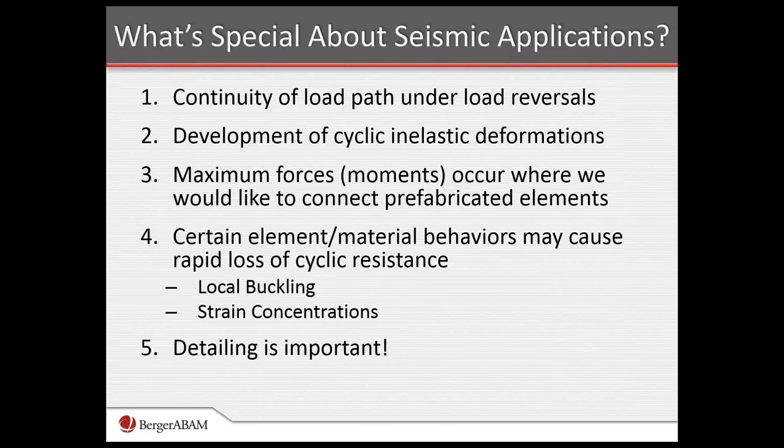We also, for higher seismic locations, are going to need to develop cyclic inelastic deformations, and the maximum forces, or in this case likely the moments, the way we think of this, would potentially occur where we'd like to connect prefabricated elements. We'd like to transport these elements as single linear elements, and therefore the connection location is often the same point where the maximum moments occur, and therefore the plastic hinging action also occurs.